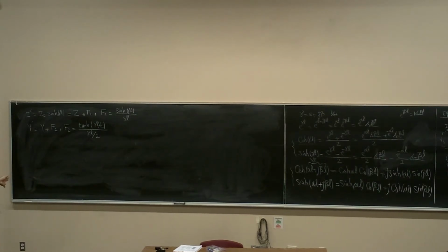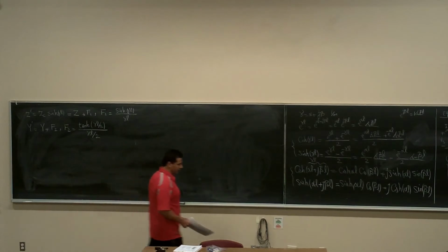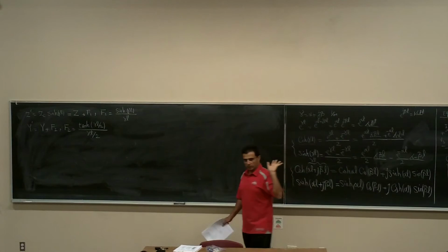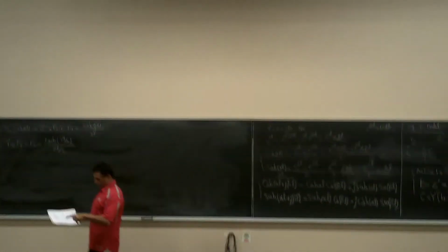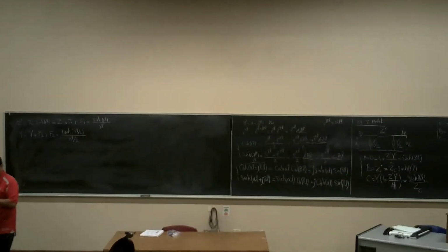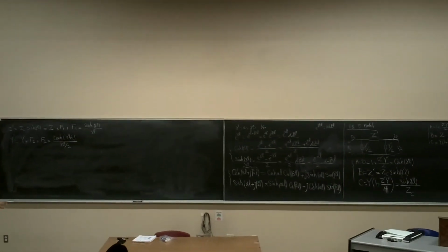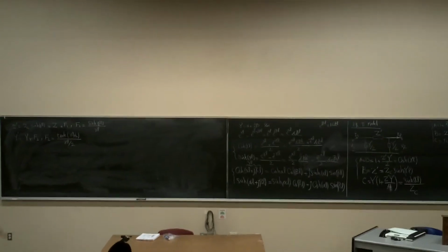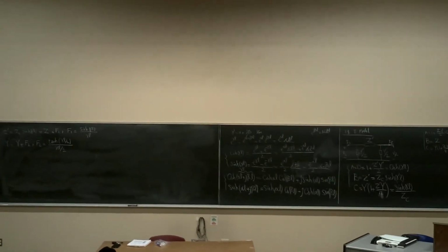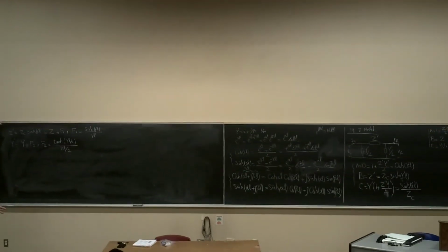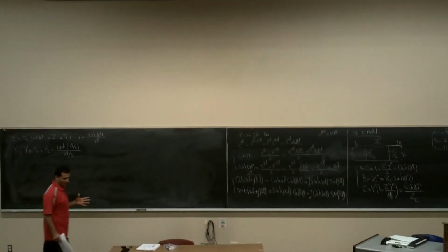The next part I'm going to teach is about the lossless transmission line and power transfer and those kinds of things. This part I'm not going to give you a question to find. But from here after, because the calculation becomes much easier, I'm going to say it's lossless. When I say lossless, the R and G are gone. It's going to make the calculation much less. There's still a lot of calculation, but much less.